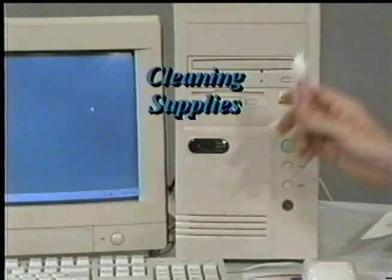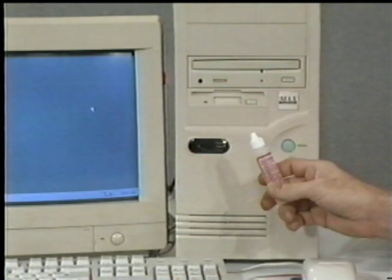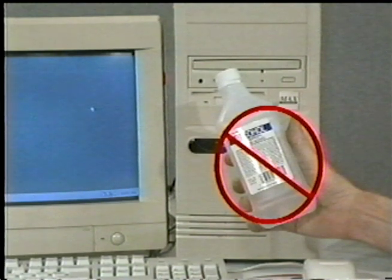This can be pure isopropyl alcohol or acetone. Never use the store rubbing alcohol for cleaning electronic parts. It can contain contaminants like perfumes and waters that are harmful to computer components.